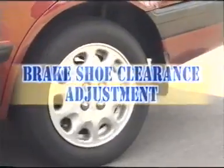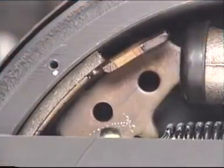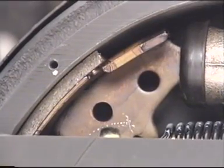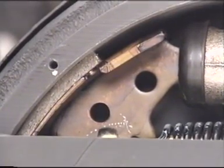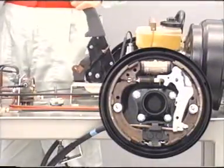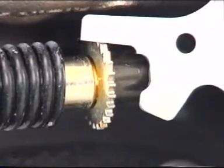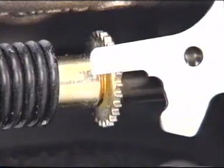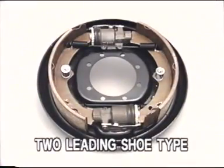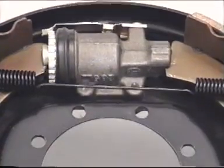Excessive clearance between the brake drum and the lining will reduce braking speed. If too small, the brakes will drag. If different at each wheel, the vehicle could be pulled to one side or fishtail. As explained before, some have automatic brake shoe clearance adjustment functions, but others must be checked periodically. The two leading shoe-type brake shoe clearance procedures are explained here.